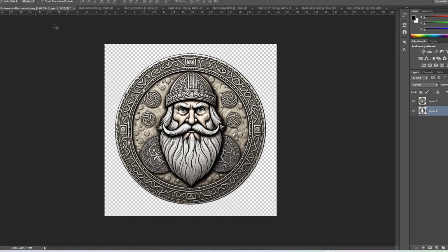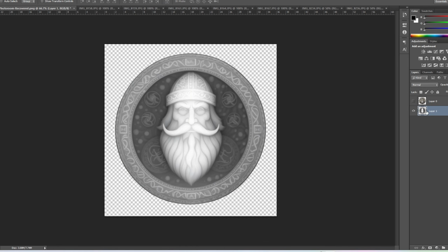And again, that is just uploading a photo, using the depth map, putting that into LightBurn, and then just adjusting your settings for what you want to do. You do a couple of passes just to take away those couple of layers of wood, and then you can get your 3D relief images looking really, really good.